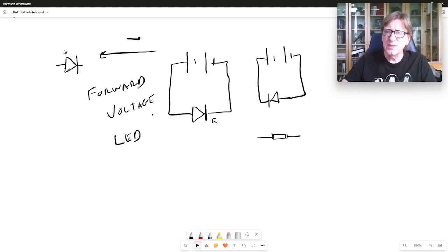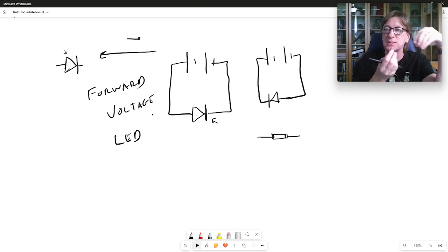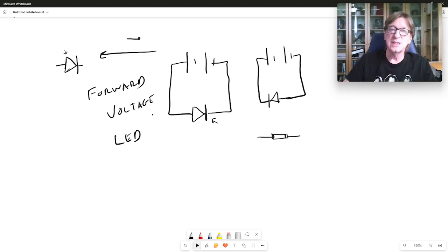So think about these different types. Think about the LEDs and the different colors of LEDs, how that works. They're different colors not because of the little clear colored dome on there, although that does reinforce the color. It's because when I drop into that energy shell, that's the amount of light, that's the wavelength, the energy of light that I'm emitting. And again, infrared LEDs are not useless. We talked about how you use them in your remote control, but in the case of robotics, your line following sensors are going to be infrared LEDs. It's going to send that infrared light out. It bounces off the paper or whatever it is. And then right next to it is an infrared detector that's going to see if it's getting that light back.